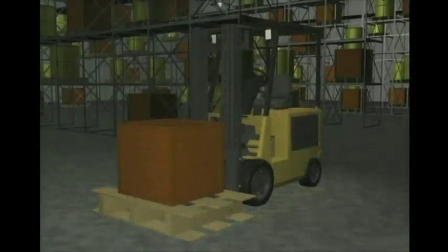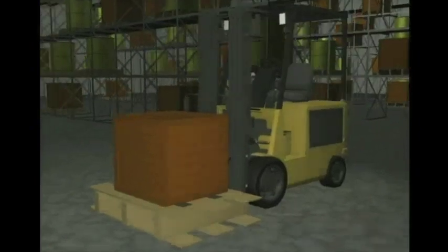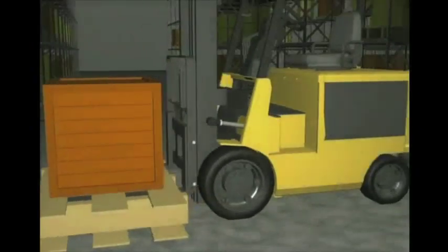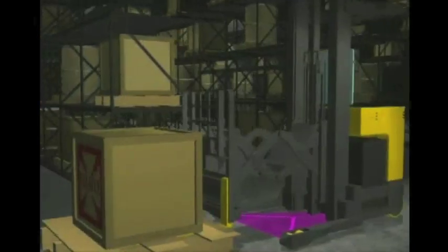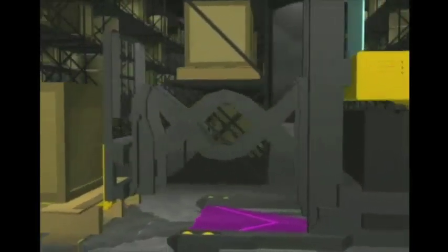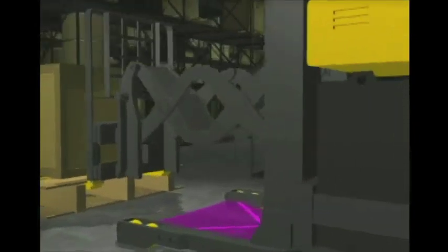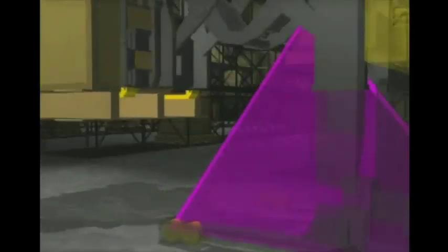A typical lift truck has a 3-point suspension, the two drive wheels, and the center point of the rear axle. In the case of reach trucks and order pickers with base legs or outriggers, the suspension points are the two load wheels and the drive tire. This forms the stability triangle base. With the added dimension of lift height, a stability pyramid is formed. In order for a lift truck to remain upright, the combined center of gravity must remain inside this pyramid.